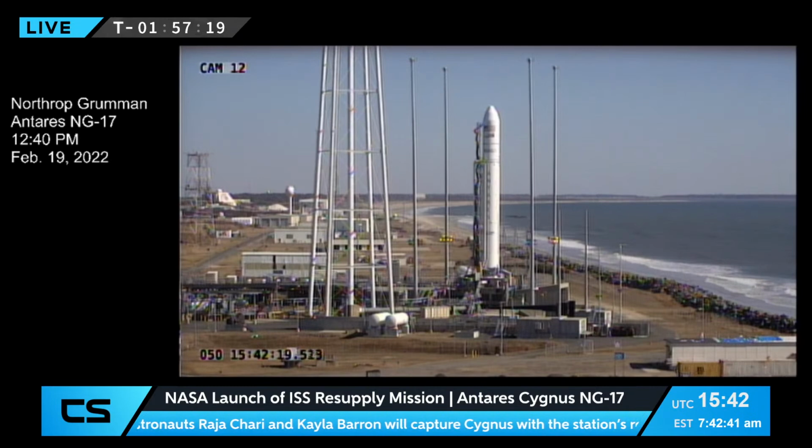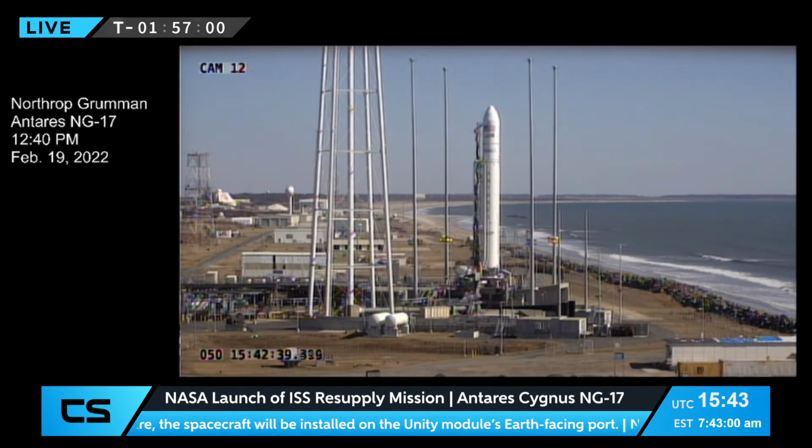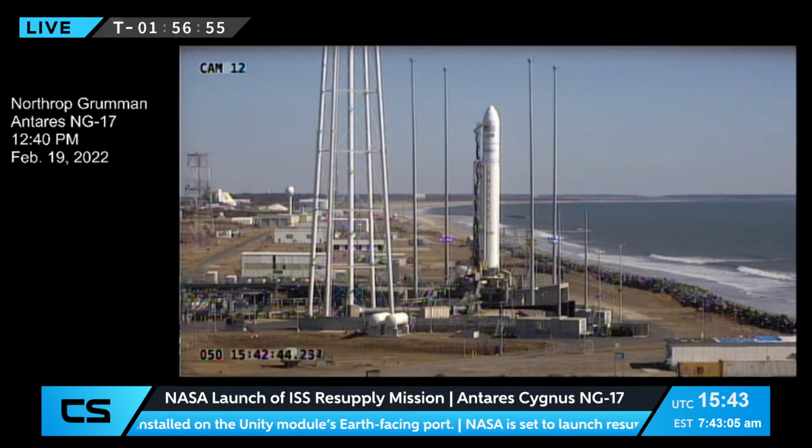Copy that. Ops 1, you can close EHS hydraulic supply valve. And I copy that. Closing 8020 on my mark. 3, 2, 1, mark. 8020 reports closed. 8020 verified closed. Copy all. Step check 220 and 221. Ops 1, transfer SMI A and B power to external. Copy that. SMI power A and B, external power on. SMI power A and B, internal power off. LC, EHS 1, hydraulic pressure has been removed from the vehicle. Roger that. We'll check 222 and 223.